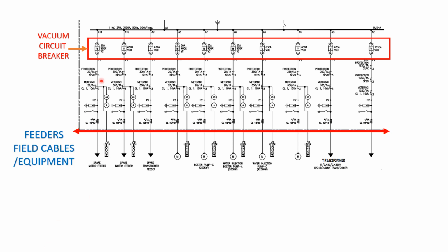And then below our panel, as you can see in the example, we have a bottom panel that is our connection where we are entering our field cables. So feeders of the field cables go to equipment. You can see this line. This is our feeder 1, feeder 2, feeder 3, feeder 4, 5, 6, etc. And after that, this is our load.